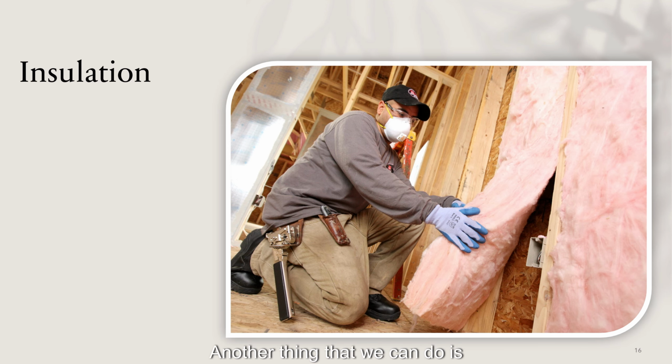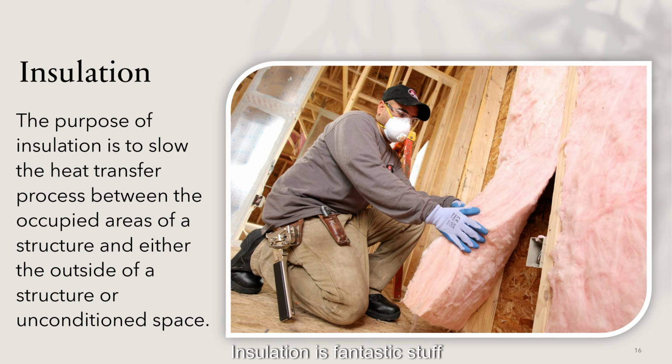Another thing that we can do is add insulation. Insulation is fantastic stuff. Make sure you wear the right PPE when you're handling it. It's not good to breathe in. The purpose of insulation is to slow the heat transfer process between the occupied areas of a structure and either the outside of a structure or unconditioned space. It's not there to stop the heat loss. We can't do that. But what we can do is minimize it.